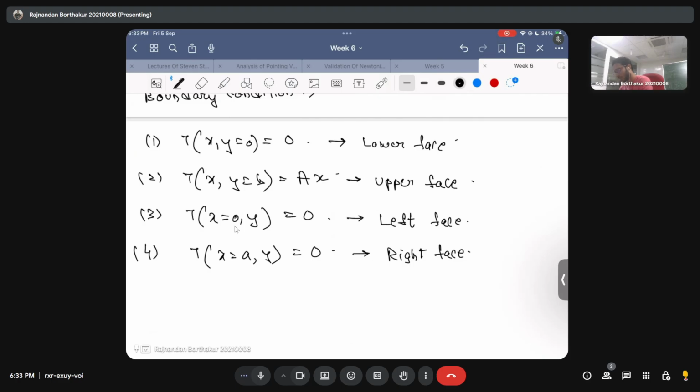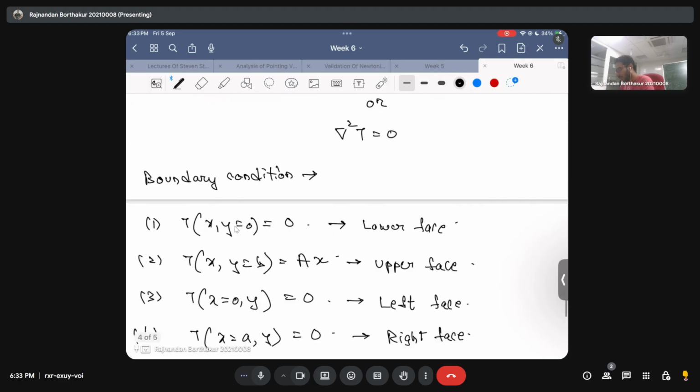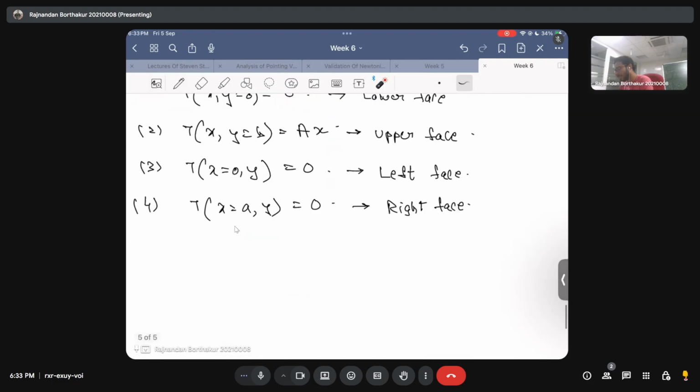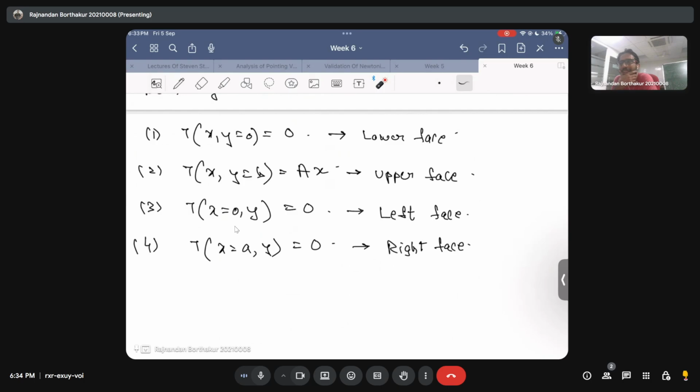Okay, so in principle, what we are trying to solve is the temperature profile for the slab, and we indeed have boundary conditions on its four boundaries. So in principle, it means that we can have a unique solution for this Laplacian equation. And if you are more interested in knowing the characteristics of the Laplacian equation, you can prove that the solution to the temperature profile will be such that it will not exceed its value at the boundaries. This means the Laplacian operator is kind of an averaging function, okay?